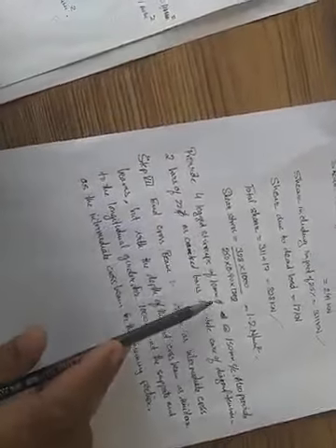So shear due to the dead load, which we have calculated as 17 kilonewton earlier on, gives me a total shear of 328 kilonewtons. So again, the shear stress you can take as force upon sigma st jd. So this gives me 1.2 Newton per mm square. To counter this, 4-legged stirrups of 10 mm dia have been provided at 150 mm center to center. Also 2 bars of 22 mm dia crank bars to take care of the diagonal tensions.